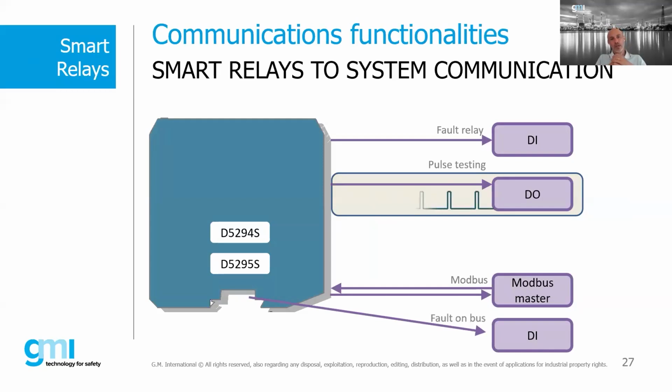The line monitoring, in this case for the relay, gives you the possibility to detect values like current, resistance or voltage that could cause a fault in your application. If you can monitor them, you can detect it and alert your system, and you can do something, of course.